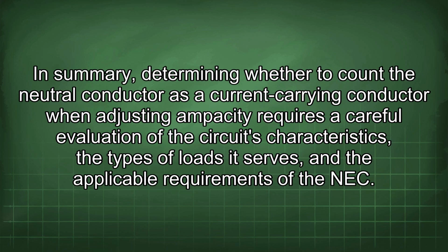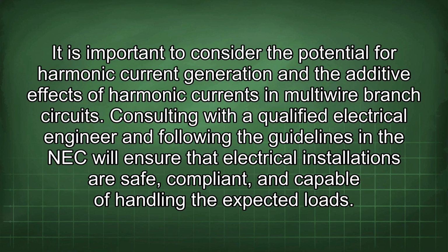In summary, determining whether to count the neutral conductor as a current carrying conductor when adjusting ampacity requires a careful evaluation of the circuit's characteristics, the types of loads it serves, and the applicable requirements of the NEC. It is important to consider the potential for harmonic current generation and the additive effects of harmonic currents in multi-wire branch circuits. Consulting with a qualified electrical engineer and following the guidelines in the NEC will ensure that electrical installations are safe, compliant, and capable of handling the expected loads.